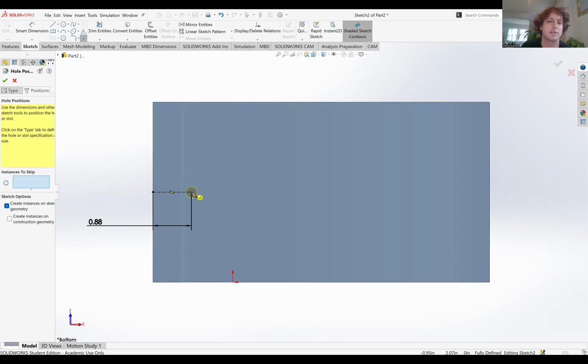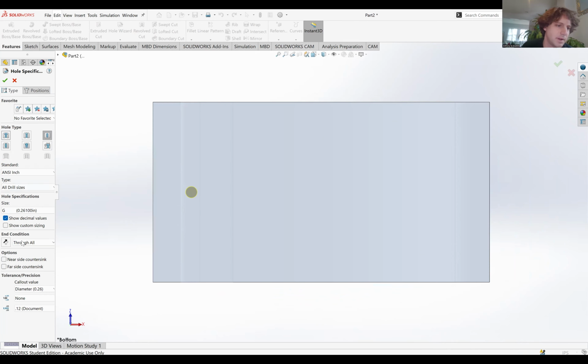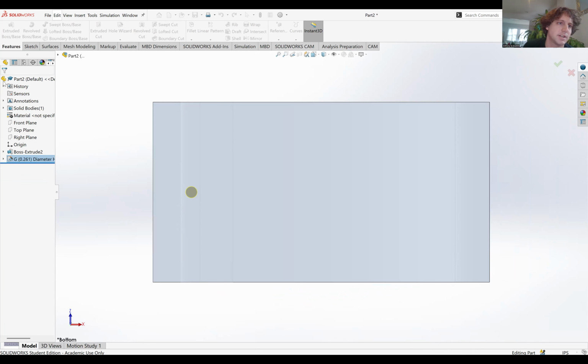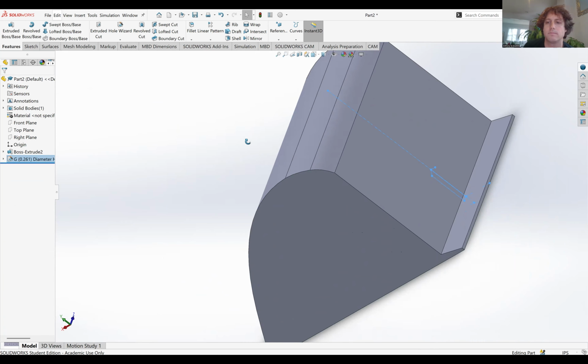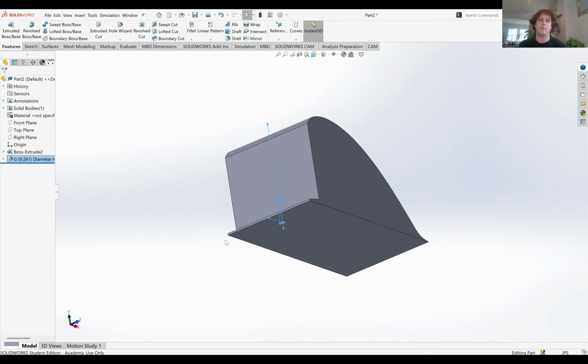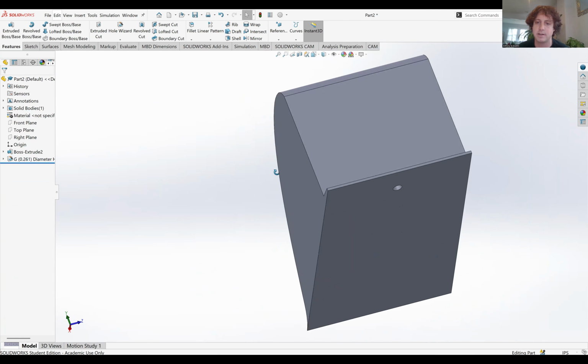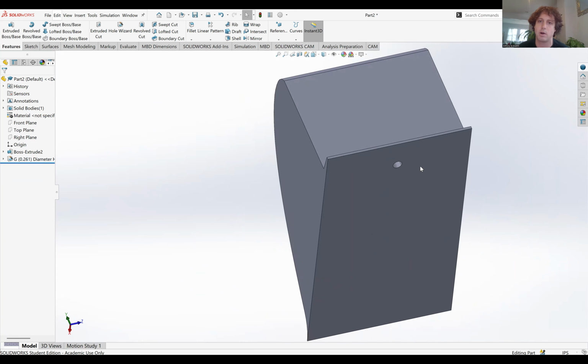Oh, I need to click on it twice. There we go. And then, oh, I'm sorry. Let's go back to type. And instead of through all, we're going to make it blind. And we're going to go, yeah, 1 inch is fine. Okay, so we're going to click check on that. All right, cool. So now we made that hole. That's going to be where the rod is going to go up through.